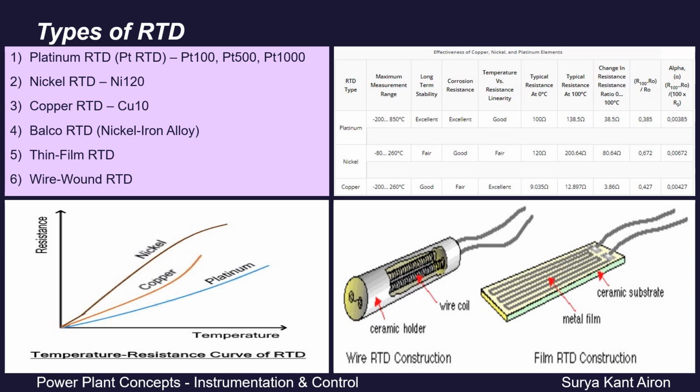While less common than the thin film RTD, they can be more robust and suitable for certain industrial environments. So what we understood is each type of RTD has its advantages and is chosen based on factors such as temperature range, accuracy requirement, and the specific conditions of the application. Platinum RTDs, especially PT100, are the most prevalent due to their high accuracy, stability, widespread application, and standardization.